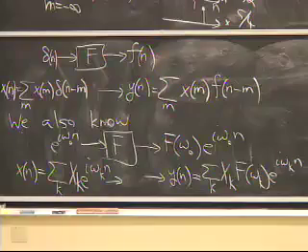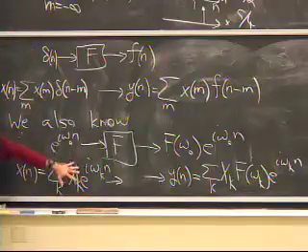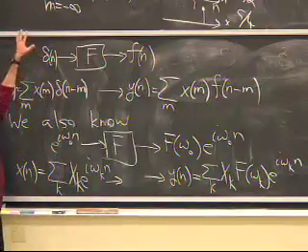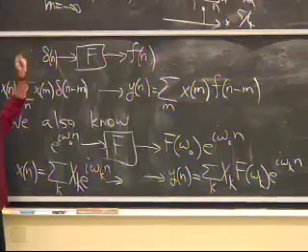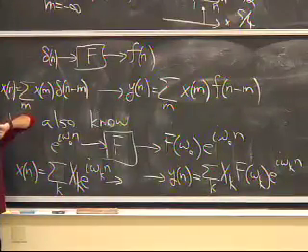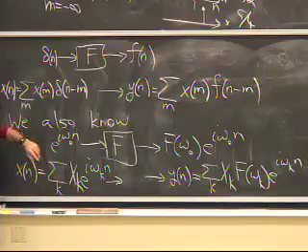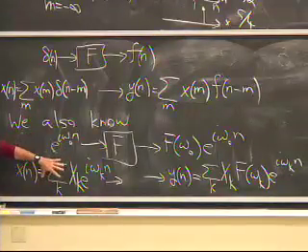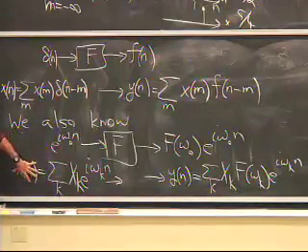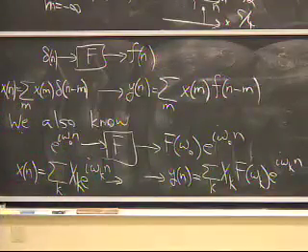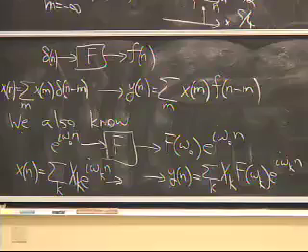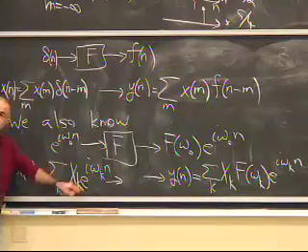So now we have the two parallel tracks. We know pretty much everything we need to know about splitting a signal in terms of a linear combination of lollipops. That's easy. What we are about to start learning is splitting a signal into a linear combination of complex exponentials. And that's the bridge between the time domain and the frequency domain, because these are now frequencies.